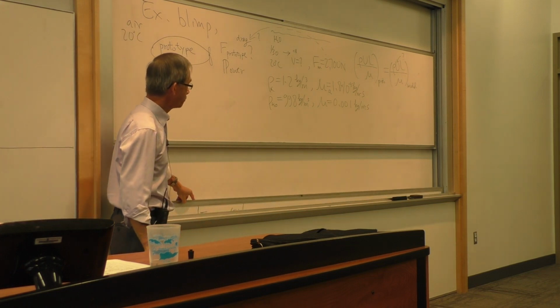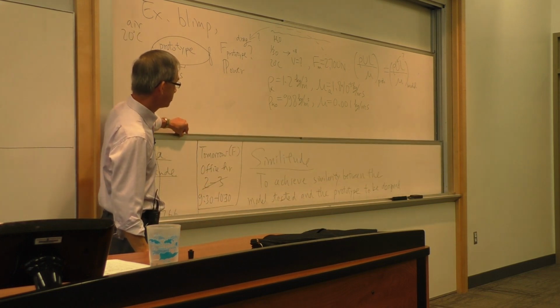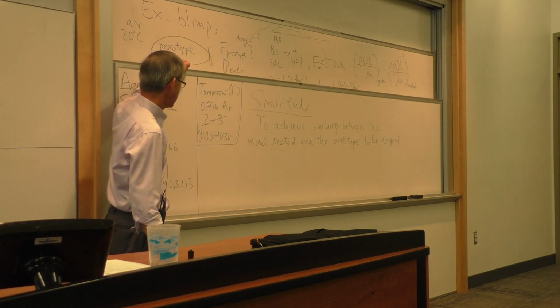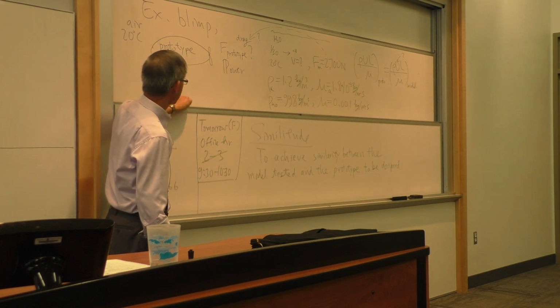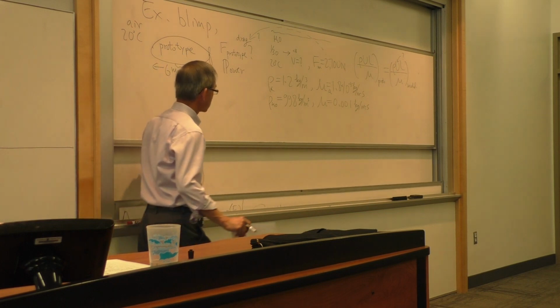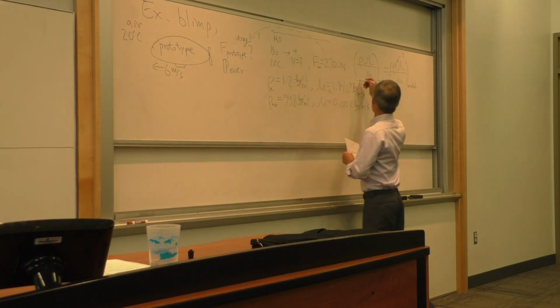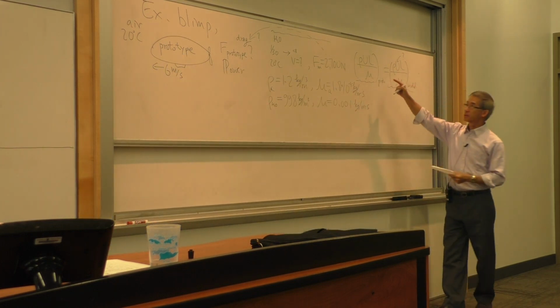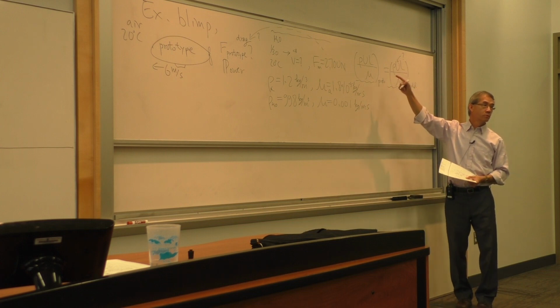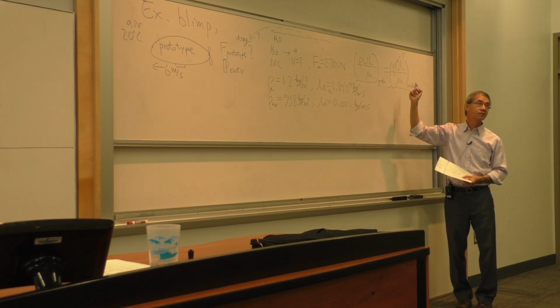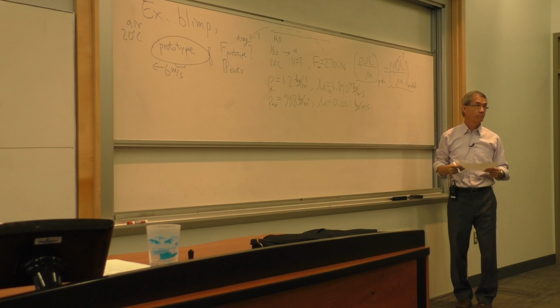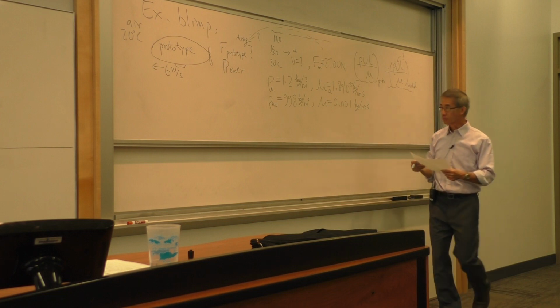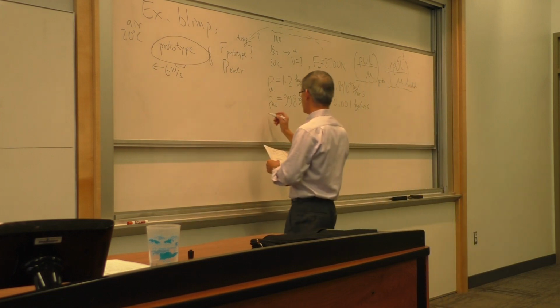This is one of the very few times that you don't have to carry the units in your calculation. And what I meant is, the Reynolds number is shown in here. As long as the units on both sides are consistent, meaning in SI, you can skip the units. And you don't have to worry about dealing with g sub c.